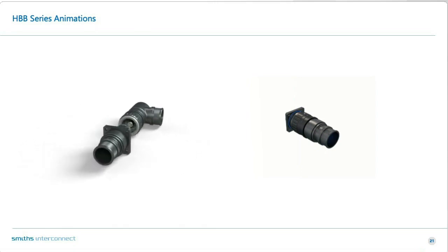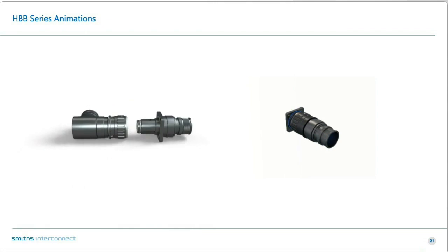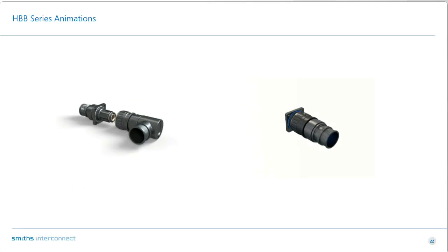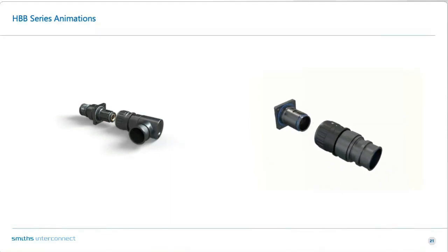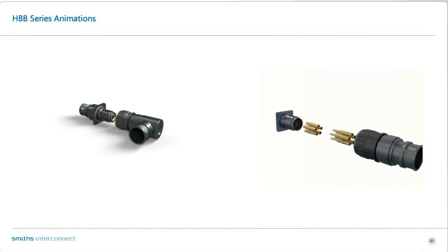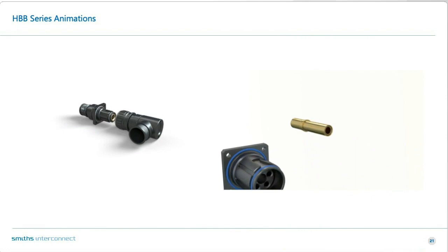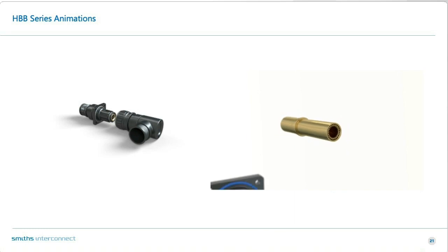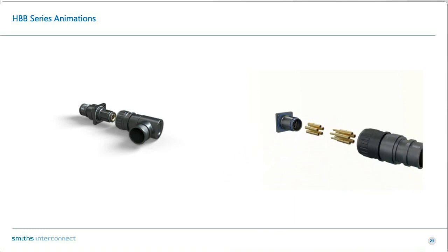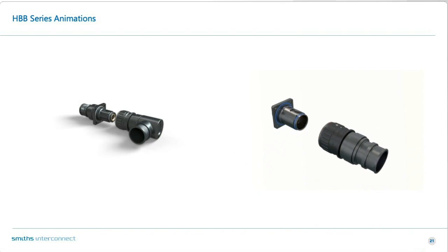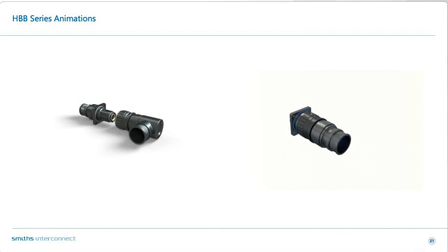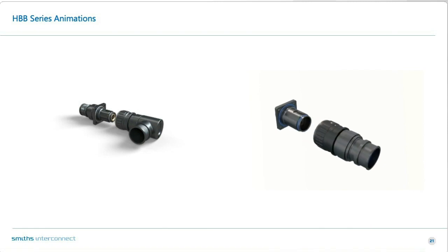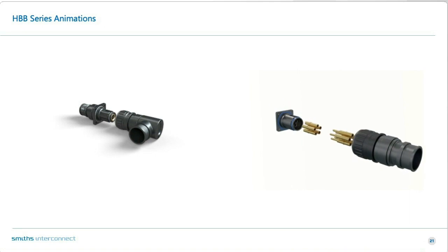The next connector on the right-hand side is the 5-pole connector, featuring a straight back shell on the plug. Here you can see the quick latch mechanism, which is featured on both the single pole and the 5-pole. Here you can see the 560 amp Hyperboloid contact, and in the center of that ring of 5 contacts are 2 safety interlocks. Keep an eye on the outer collar on the plug. As it mates, it will move out of the way. It is a push to mate connector, so it rotates itself and then clicks in place. Then you just rotate the collar to unlatch and pull it off. So that's the single pole and the 5-pole.